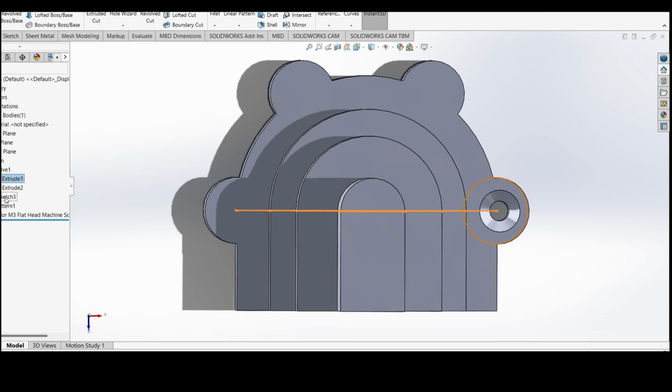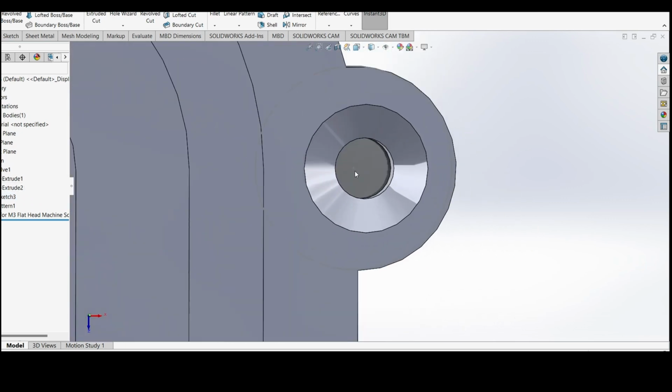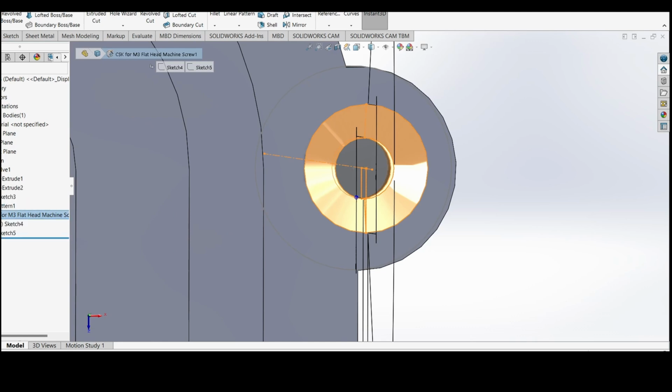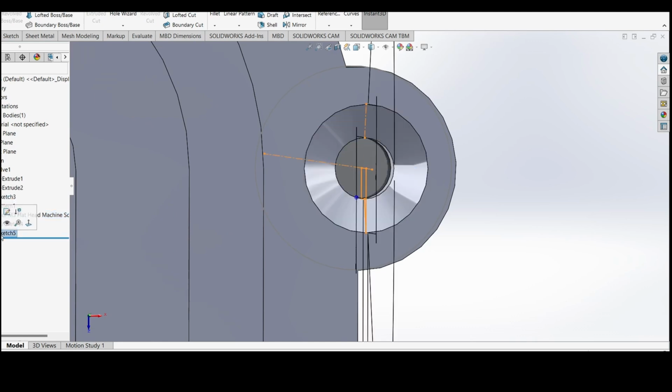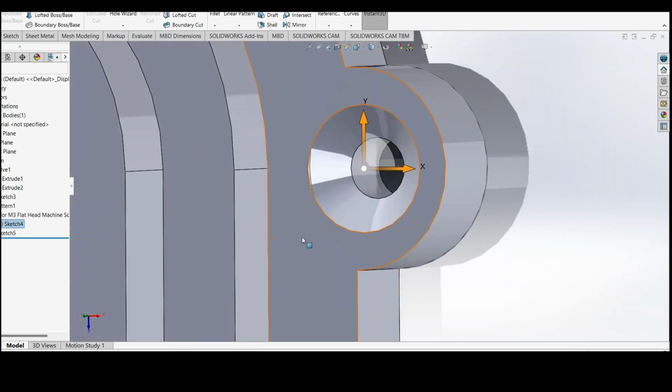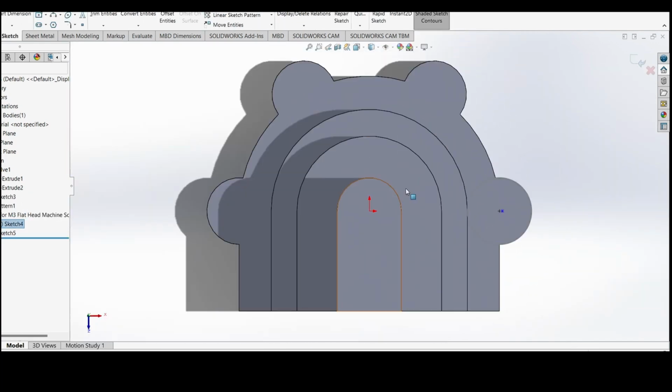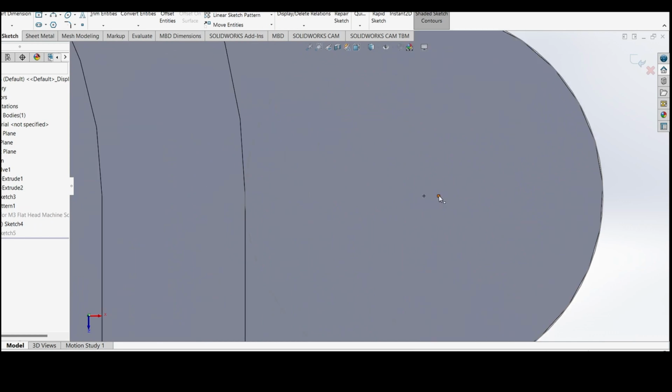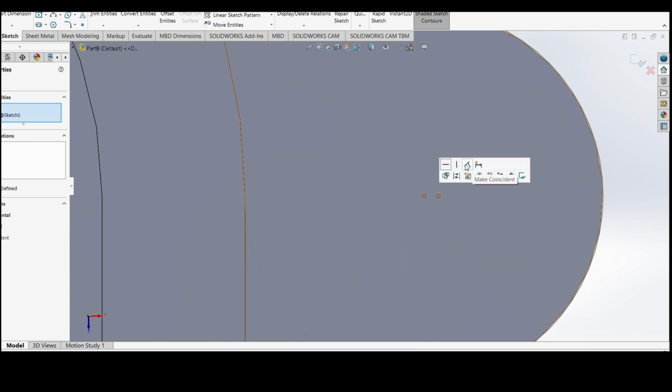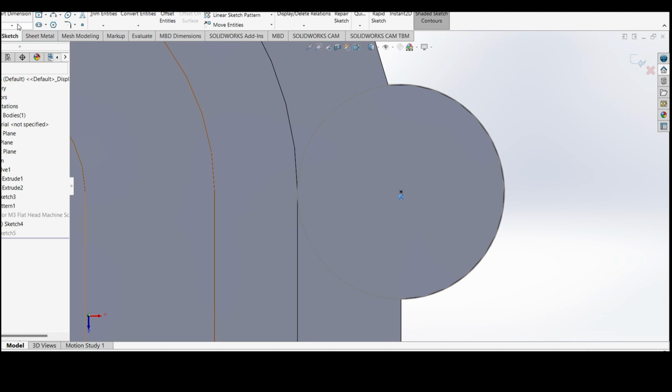by turning on the sketch where I drew the circle. When I say turn it on, I mean make it visible. Because by making it visible, I'm now able to select that point in the sketch. If I come back to my Hole Wizard and find the sketch where I made that point, I can edit that sketch. There we go. And make these 2 points coincident. So now it's defined and it's in the center.